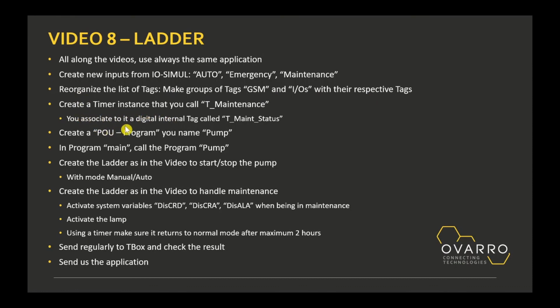You associate to it a digital internal tag as status. You create a POU program you name pump, and in the program main you call this program pump.